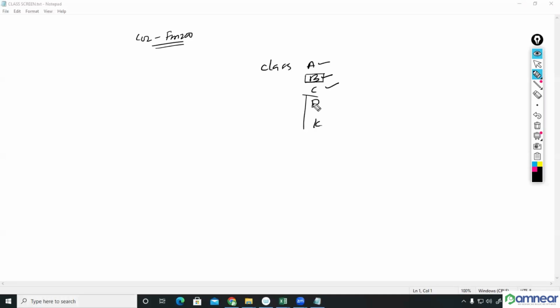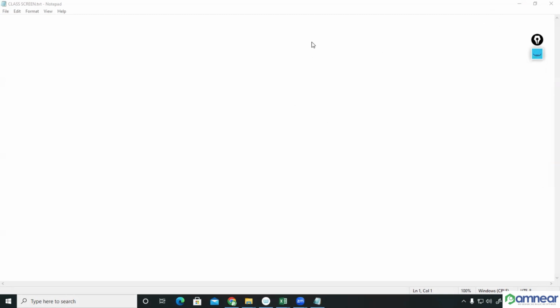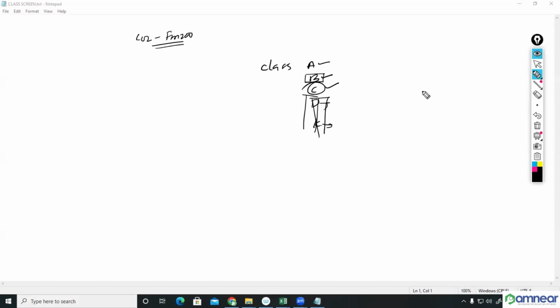Class D is combustible metal, where we have to use special purpose dry powder, and for class K we use wet chemical type. Class C is energized electrical equipment only. There also you can't use water. You can't use liquid type fire extinguishers on class C because they may cause short circuits in the energized electrical equipment. That's why there we can use gases.